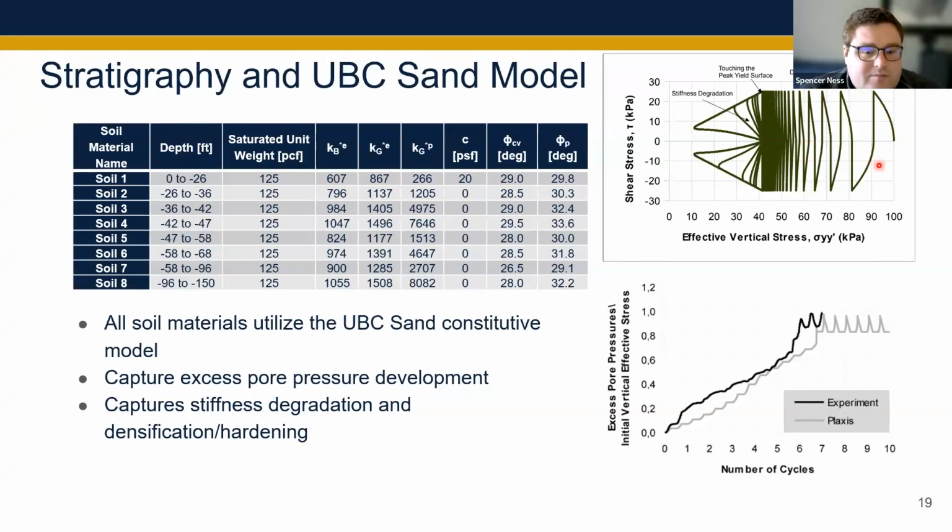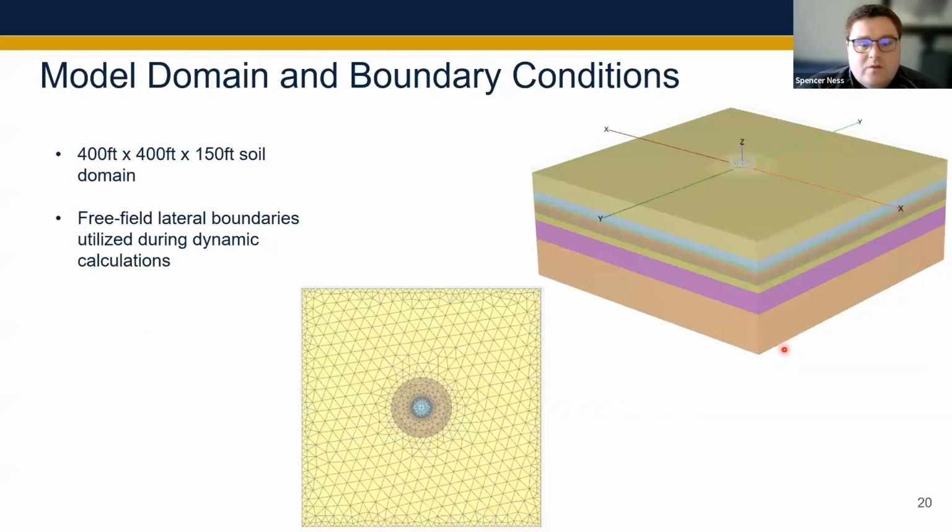This is taken from the development documentation around the UBC sand model. But as we cycle these loads and change some of the effective vertical stresses that we're seeing, things are behaving as we would expect. Similarly with excess pore water pressure buildup and those parameters as well.